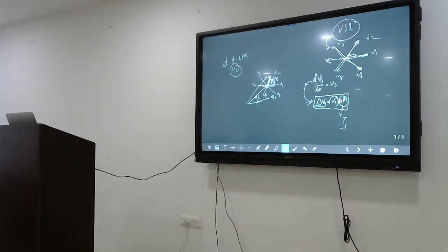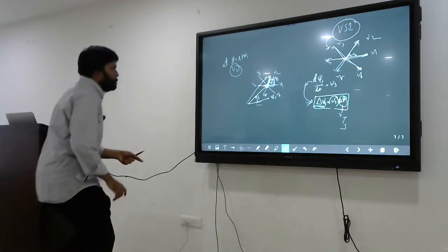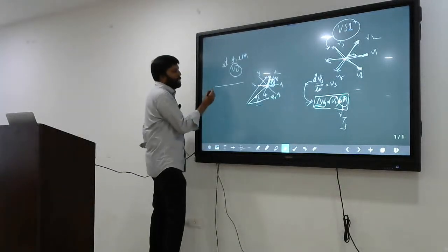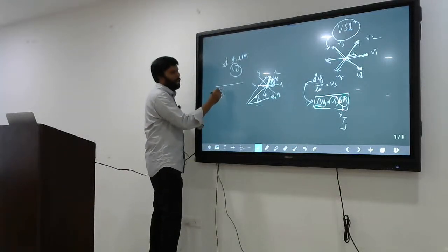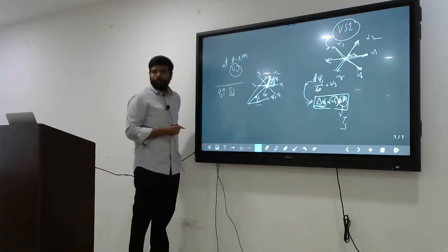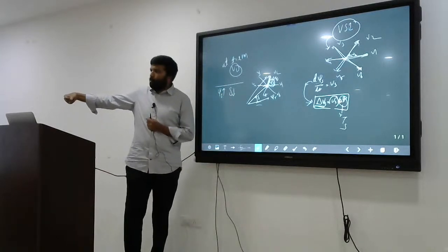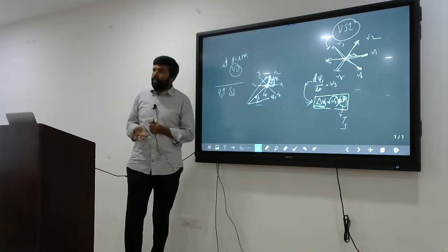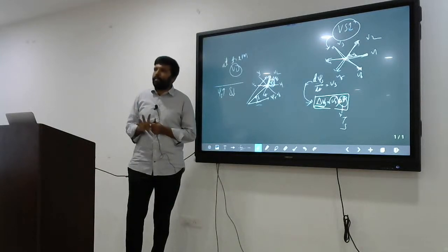If you want to increase the flux and decrease the torque, which voltage vector is mainly responsible to satisfy your requirement? Anyone? So the aim is, in the next instant I want to increase the flux vector length, but I have to decrease delta. My aim is that flux I need to increase, but torque I need to decrease.